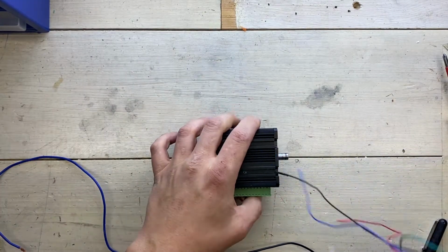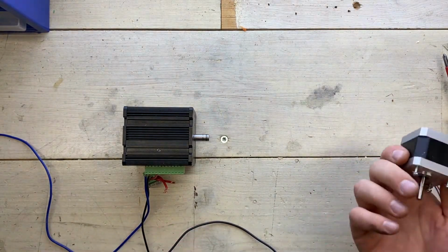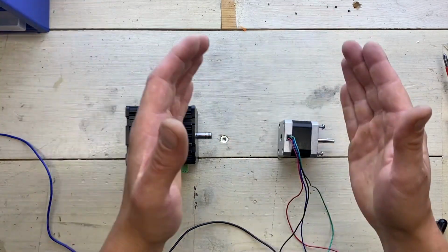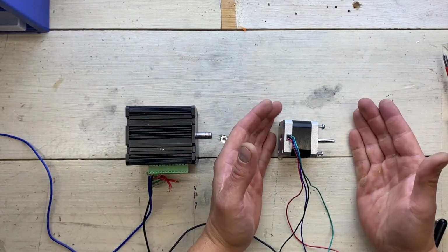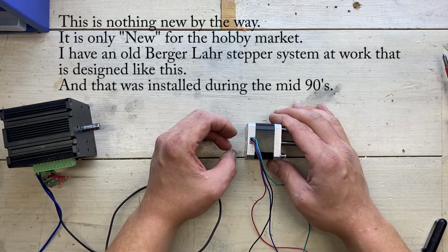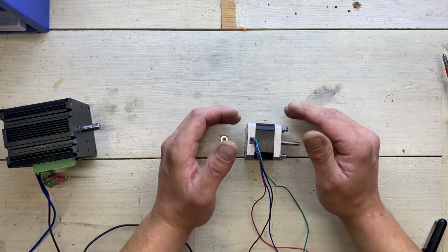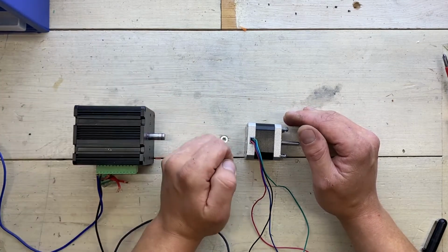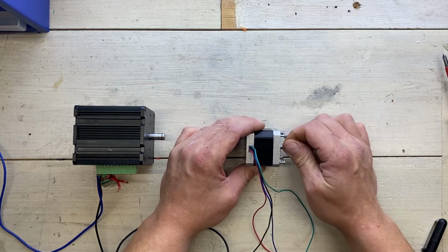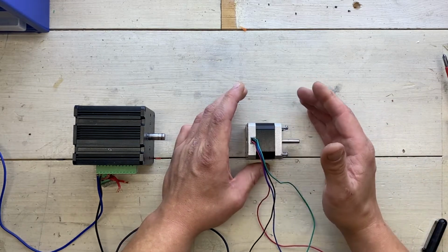There is also something called a hybrid servo. And these started popping up a couple of years ago, mainly from China, and with the definition of a servo system being a system with feedback, then they are also a servo. But what they've done is take a stepper motor and attach an encoder on it for feedback. And this has some upsides, but it's still not really as good as a dedicated AC or DC servo. Because a stepper motor is generally less powerful the faster it goes, and it will lose more steps, basically lose its position more the faster you go with it.